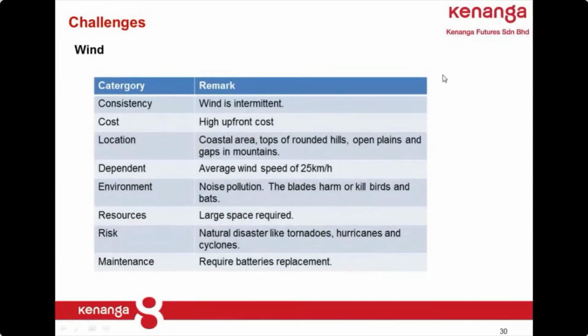Okay, and in terms of maintenance, first, after the kinetic movement energy is generated into electricity, you will need a battery to store the energy generated. Due to the design of the windmill fan tower, only a small battery can be installed inside the tower, and the lifespan of this small battery can be about 4 to 5 years. A better quality one will be approximately 10 years. After that, you need to replace it. And another thing with the battery is that you can only store the energy for hours, and you cannot store it for days or months. That's the challenge for wind energy.